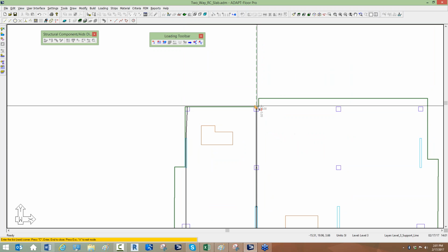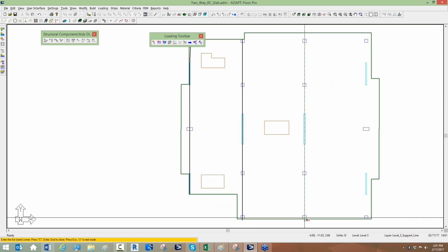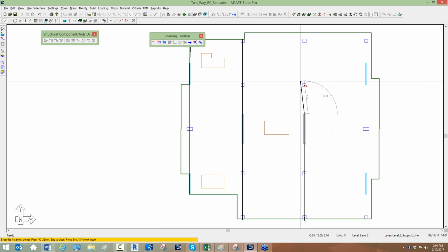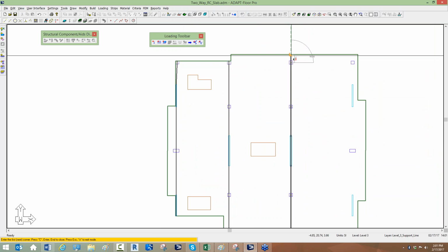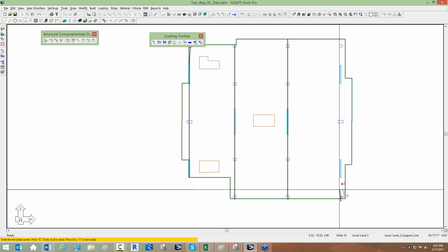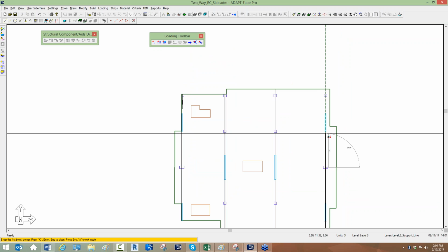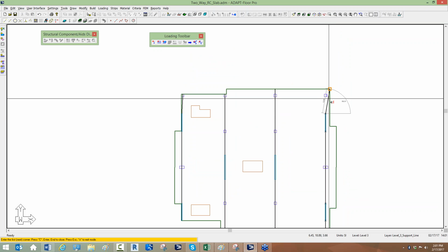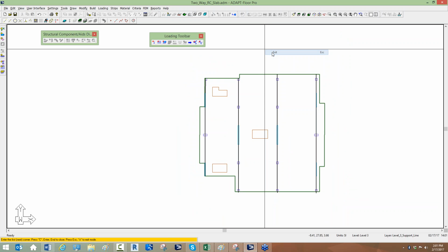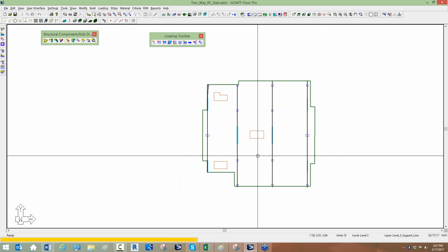There's also a wizard which allows rapid input of support lines. I like to do this manually just to show those who might be new to the software how these should be done without having the computer just do it for you and relying solely on that method. So we're just snapping again to the support points. This just simply defines the spans along each of the strips. And in this case, we're not going to add any splitters. We'll just leave it as is.